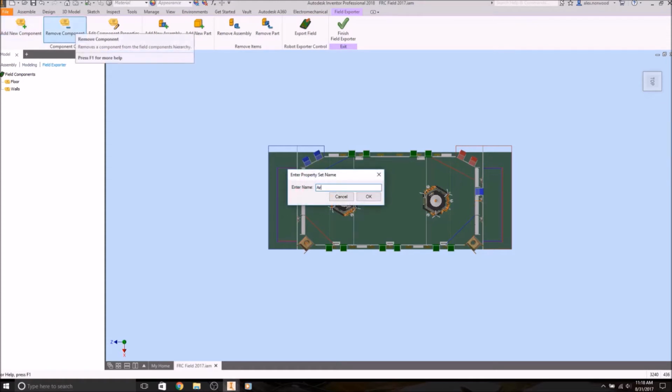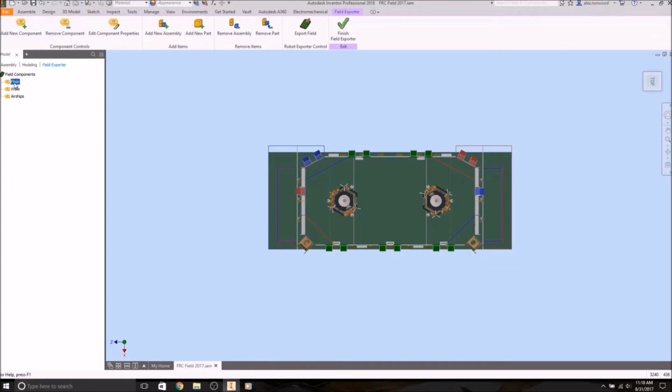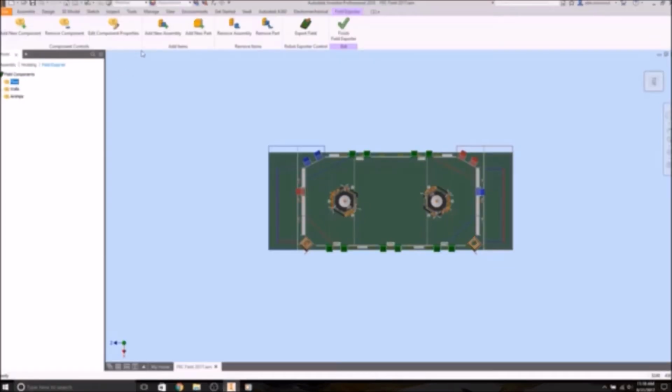One major difference between components themselves is their collider shape. Synthesis supports 3 different kinds of collider shapes, or meshes: a box, a sphere, and the mesh collider. The box and the sphere try to fit themselves to each model within the component and take up at least the same amount of space. The mesh collider fits itself exactly to the model, but it takes longer to generate and slows the simulator if